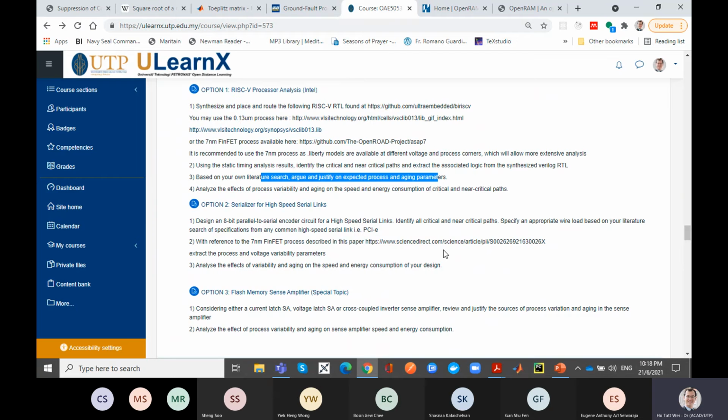But how you're actually going to apply it? Let me give you some hints. For aging, you'll be looking at regions where you have hotspots in current. Hotspots in current, you probably know, are those where big transistors draw bigger current. If I have a region of the chip with more big transistors, then that part may have more aging potential, so you can circle it and flag it as a hotspot. I know that aging is related to negative bias temperature instability. Or it so happens I need to use a lot of unit size gates, which are a little more susceptible to these effects.